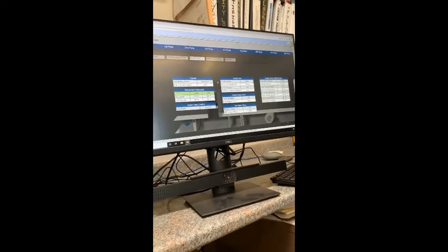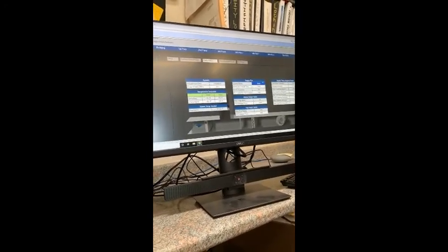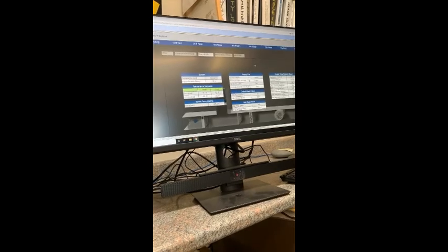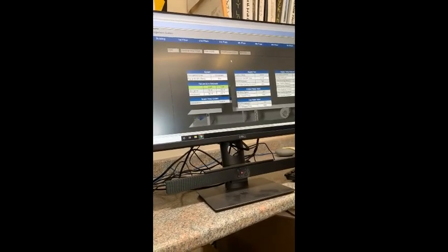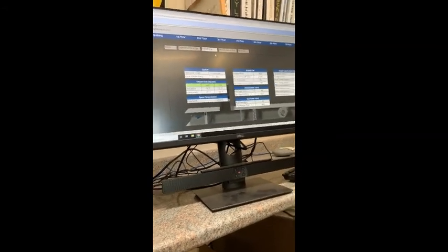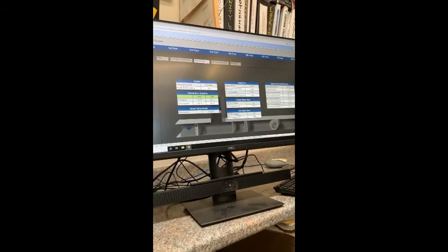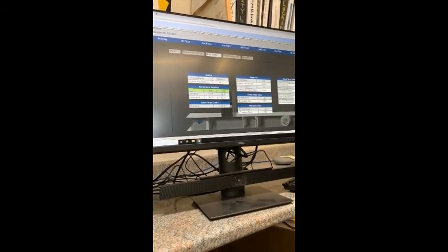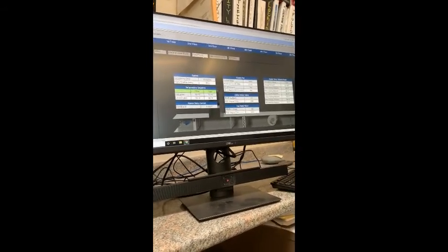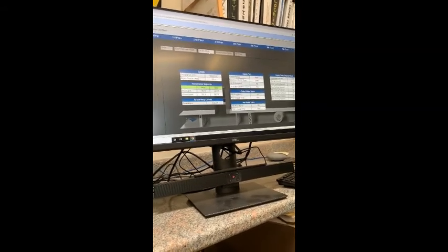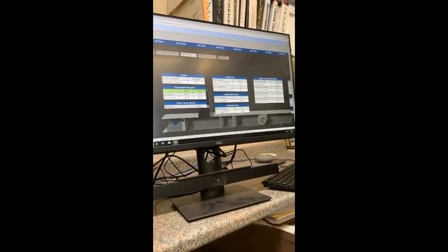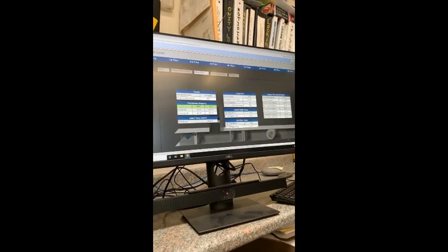There you can set it to basically unoccupied. You would uncheck occupied, and I think you could set the supply fan to off too. There are a few different ways to get the same results. Say there were 10 dorms that were going to be used during the summer, for some sort of internship, and people were being housed there. You could set them all off, and then go to those individual ones and turn them back on, because it's doing a set to everything, and afterwards you can just turn those individual ones back on.